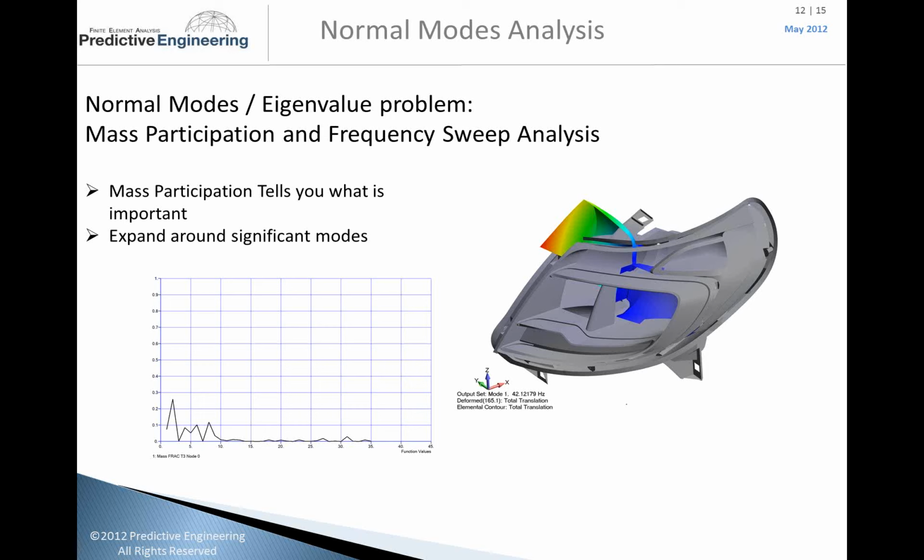This is where it's useful to look at the shape and also the direction of your applied loads. Some people say, oh no, we have this load operating at 20 hertz going this direction. And you look at the structure and say, well, even though we have a mode shape at 20 hertz, the mode shape is moving at right angles to that load. So it's null and void, which can be real handy.